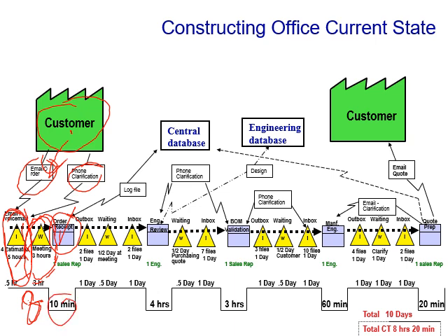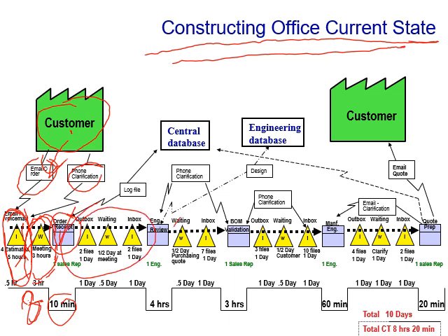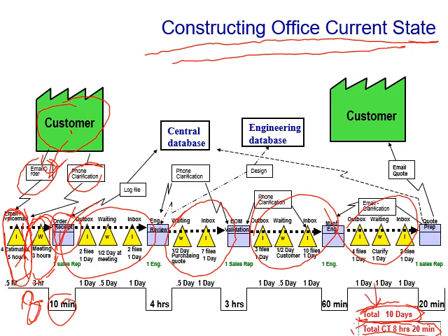So in other words, we can construct a service value stream map. However, as you see here, every process and every waiting is divided into several waiting times. For the case that we see here, the total production time, the cycle time, was 8 hours. However, the total process lead time is 10 days. It takes 10 days to process this one. In 10 days, we need only 8 hours to do the business.